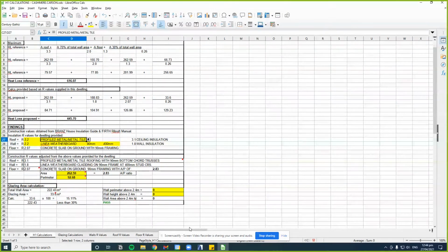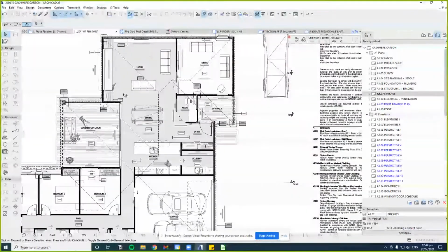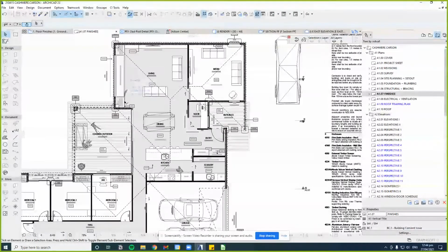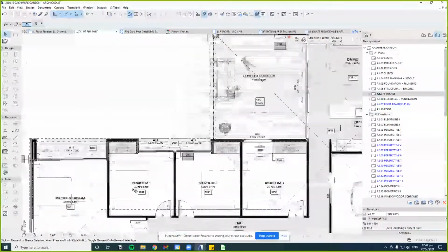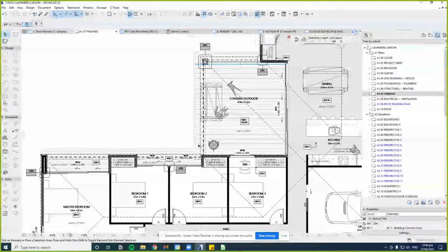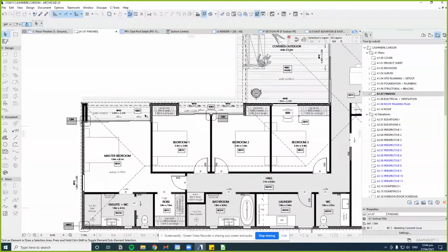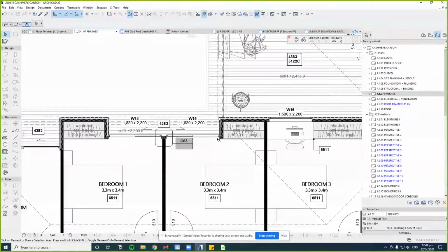My roof cladding on this job is profile metal, I know that. And then there's a combination of claddings on this job. So I have on this job two types of vertical timber. One's a painted timber, the other one's a cedar, and then we also have a James Hardie product in some cases. The James Hardie product is actually over these areas here, so that's not actually affecting the external envelope of the build. So in that case, we just need to only use the claddings that are a part of this external frame.